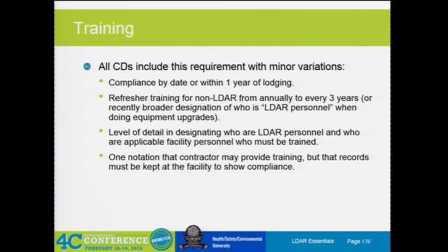Does your maintenance man need to understand the regulations and every bit and piece about everything? No. So what a lot of folks did is they made custom trainings. You have your maintenance staff and your operations staff training. They need to know what OELs are, why they're important to look at. They need to understand the 5 and 15-day repair. In some of the consent decrees, and you'll find this when you read them, some of them have a 30-day repair requirement if it didn't trigger a federal leak.